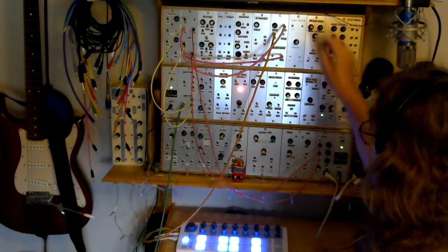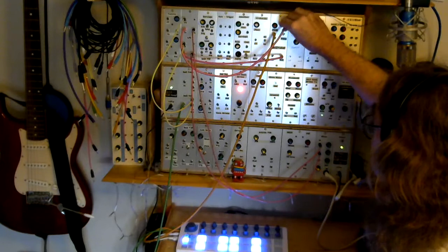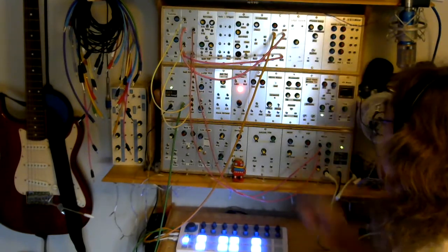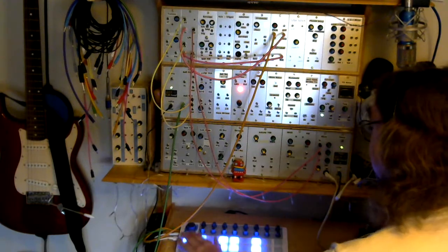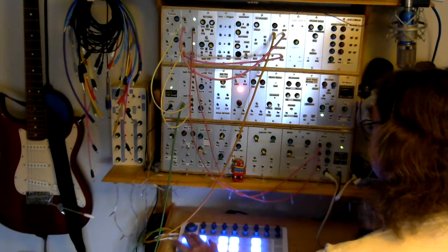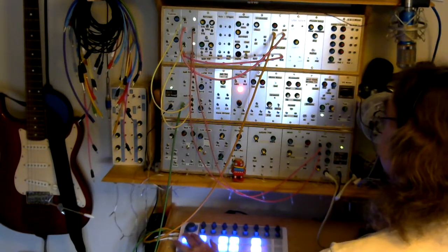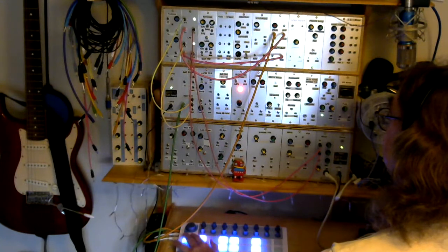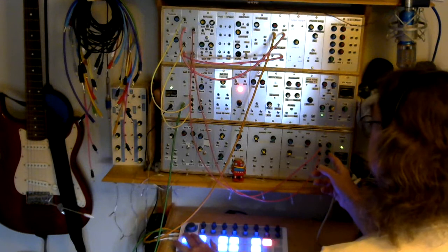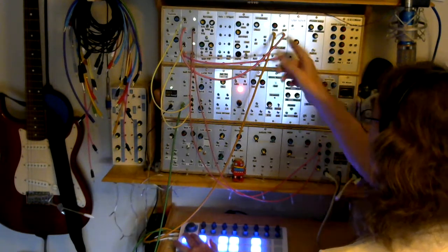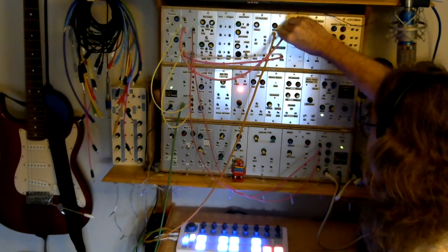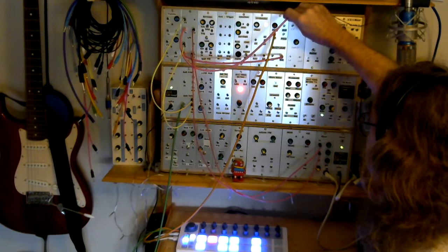What I can do, if you want to hear what the pulse output sounds like, is plug into it. This will now have disconnected the Octivator, so all you will hear is the pulse output. Of course, I've still got the sub-octave dialed in, but by plugging into the pulse, it automatically disconnects the binary counter, the 4040.